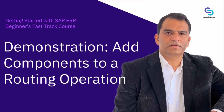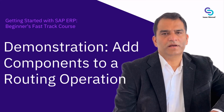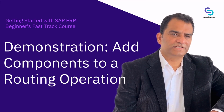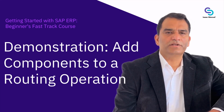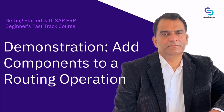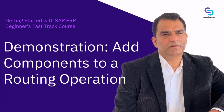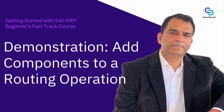Welcome to this session on how to change a routing in SAP. In this lesson, you'll learn how to update the sequence of operations, verify work centers, and assign material components to specific production steps using the standard SAP routing change transaction. These tasks play a critical role in ensuring accurate production processes, optimized material flows, and on-time manufacturing.